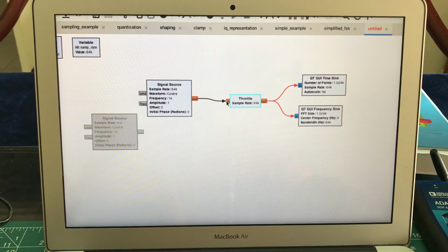That also changes this. Just click on this, and by moving your arrow keys, this will also change the type. So right now it was light blue. By moving my arrow keys, I can change this to float. As soon as the types are matched, you will get this wire to be black, which means there's nothing wrong.